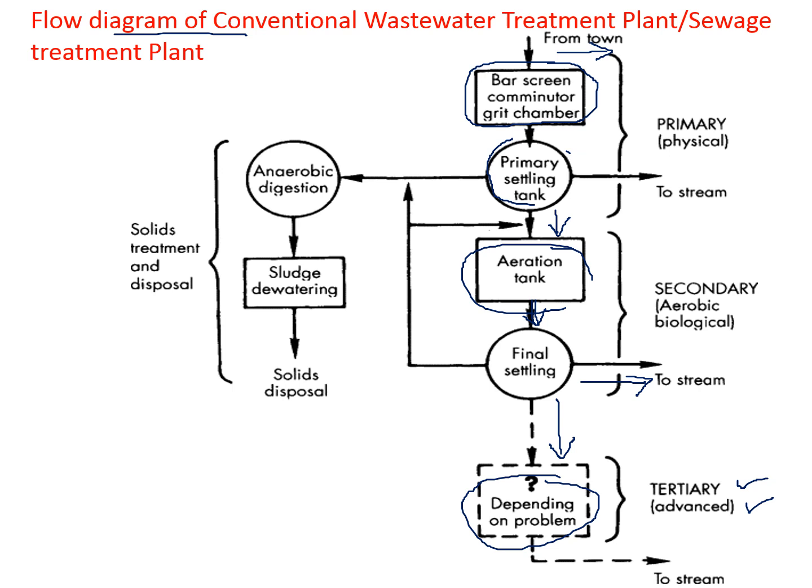In the final sedimentation tank and the primary sedimentation tank, sludge is formed. Both these sludges are collected together, and then treatment is applied, generally called anaerobic digestion. A certain amount of sludge has to be recycled to the aeration tank, because in the activated sludge process the active mass of microorganisms is very essential. So this return sludge at the inlet of the aeration tank will maintain the active mass of microorganisms required for the degradation of organic matter.